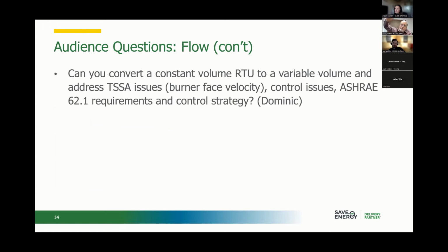It doesn't make it quite down as far as it should, and you don't have the mixing effect into the space. And if you don't have the mixing, what you might have is that air short circuits, and it gets pulled out by the return side of your system before it should. So it becomes a little bit of a tricky issue, and there are other science issues involved with that.